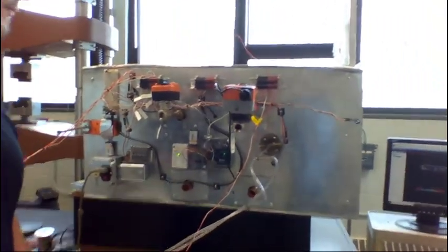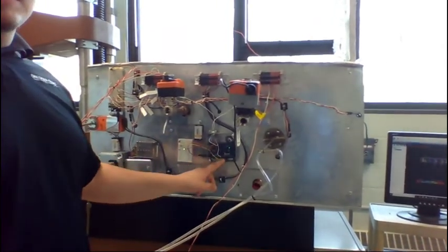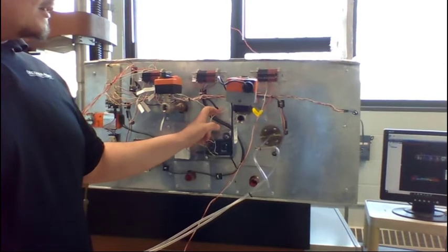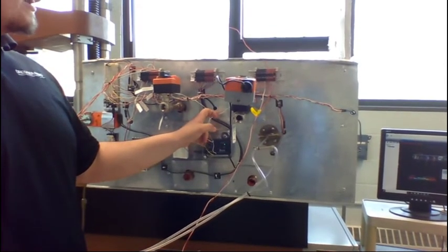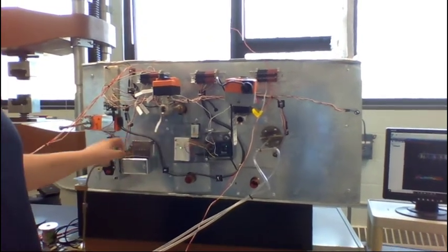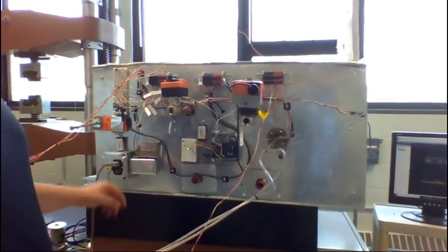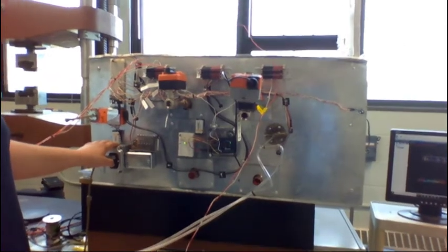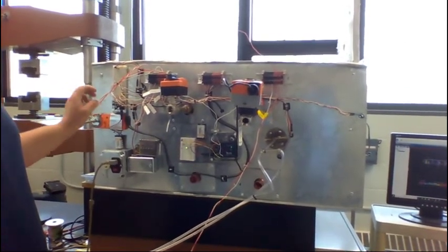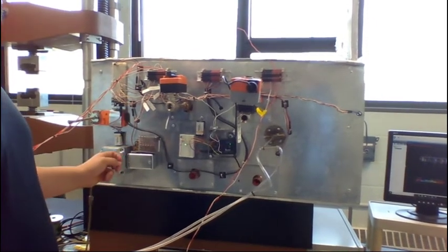Over here we have the actual air handler unit. This is the Arduino, which does secondary controls separate from the PLC. We feed the PLC into this control right here, which is an analog 0 to 5 signal. We did satellite batteries here in order to save down on the wiring. Here are some more connector blocks, which connect into the transducers.